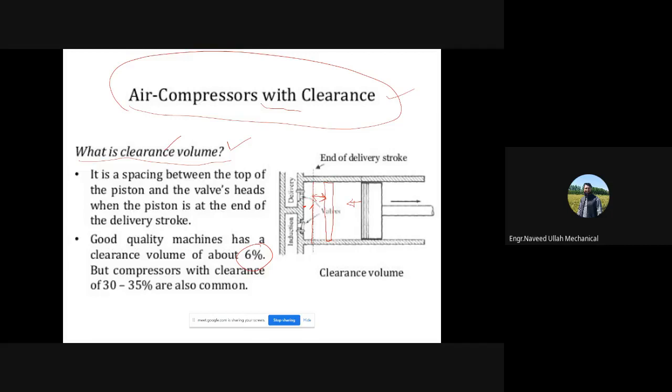So now at this position, when the piston is at the end of the delivery stroke, ये delivery stroke है ना, यहाँ से ये delivery start हो जाता है ना, you remember, right? Because this is induction, compression, and from here delivery starts. This is delivery stroke. So not at the start of the delivery, but at the end of the delivery stroke.